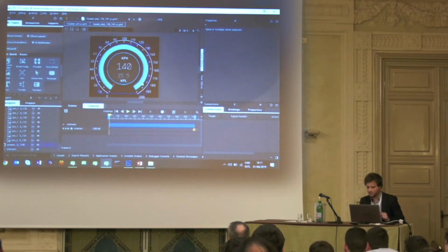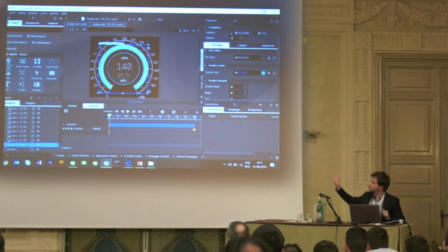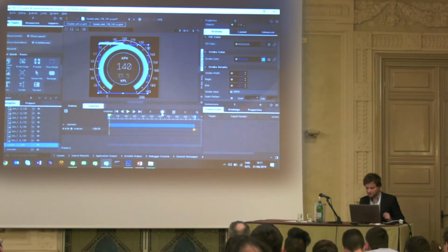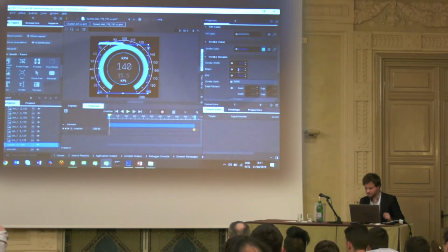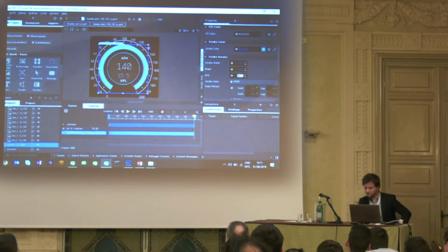And I'm going to do the same thing with the arc. So the arc item, which is, by the way, something specific to the Design Studio. This is not part of Qt Quick in general. It only exists within Qt Design Studio. And I'm going to insert a keyframe. So basically, the end of my arc at frame 0 should be the same as the beginning, so it should be minus 60. And at the end, it should be, I'm not sure, I think it's, yep, 240.